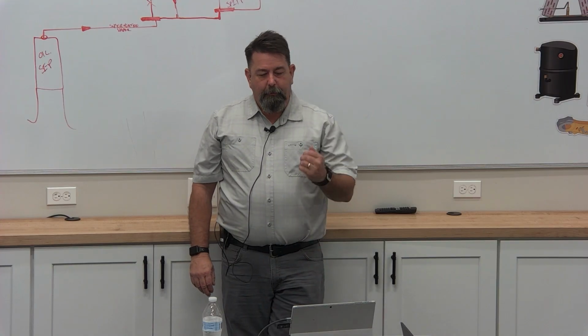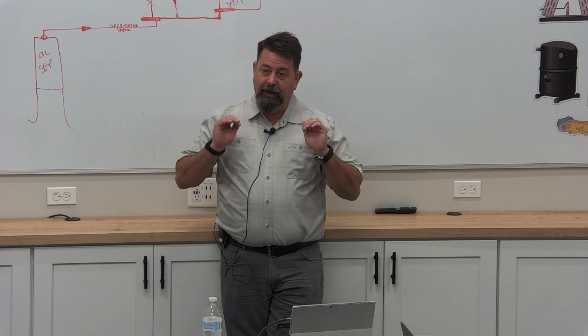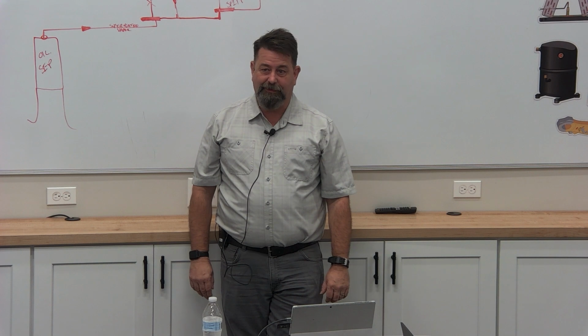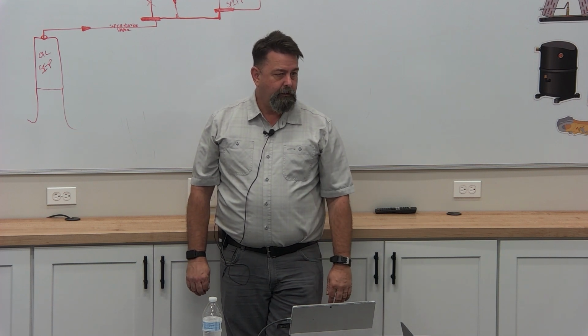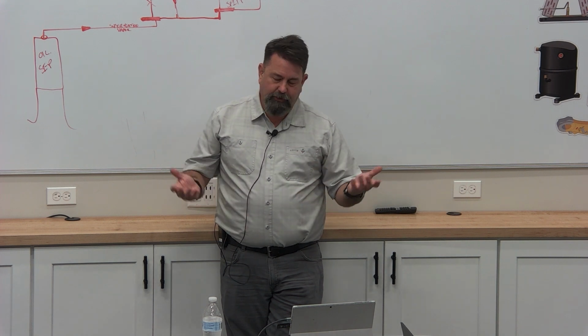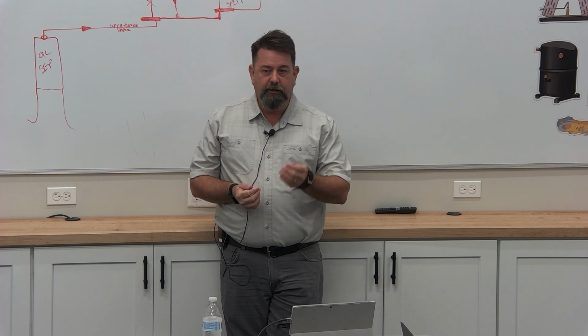That means if I'm missing my shelves, if I start up a case with no shelves, my air curtain is going to be all messed up. It is not going to be even close to right. Now, does that mean I can't go ahead and fire the case up and start dialing stuff in? Sure, you can do that. But your final EPR settings and TXV adjustments are going to be wrong.